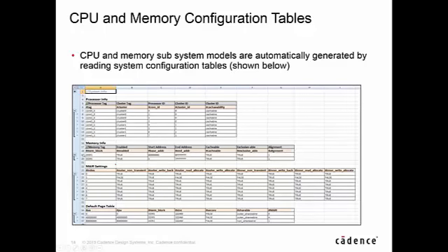Then we go into the resources of what memories are available and what address ranges those cover, and then we go into the memory access indirection register settings to get those set up, and also the default page tables, as Adnan was talking about, and the whole DVM configuration capabilities that need to be set as well.